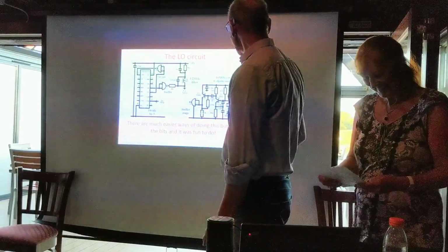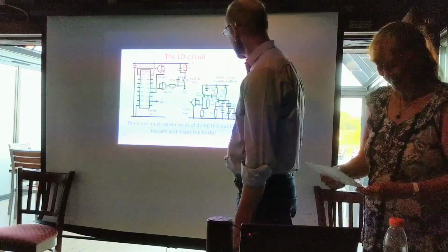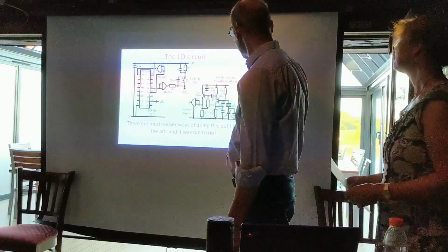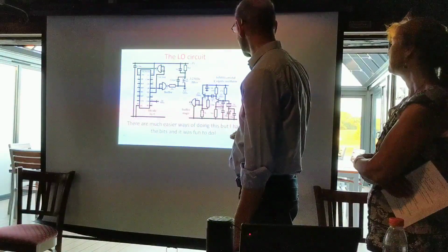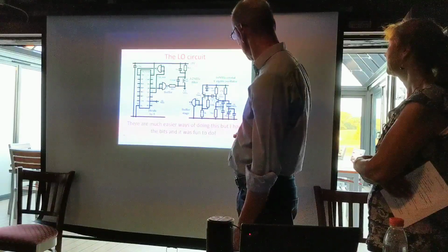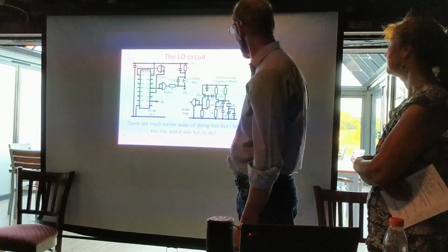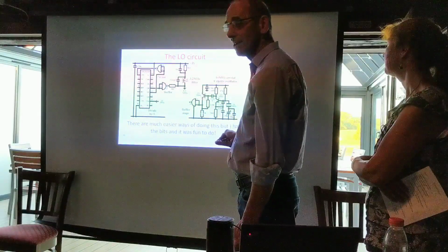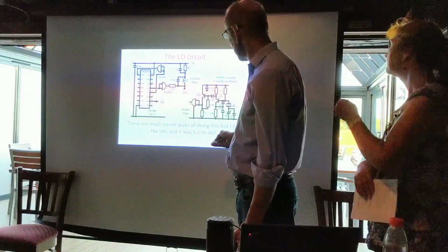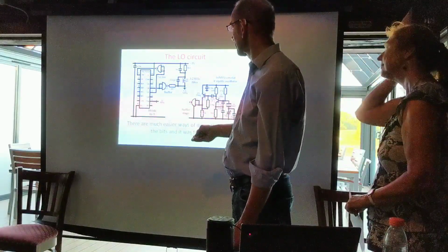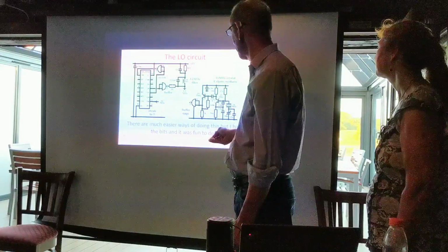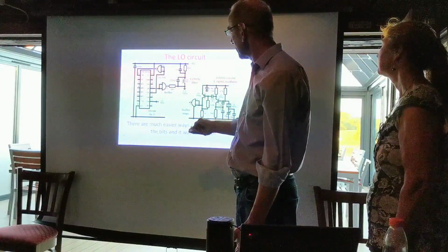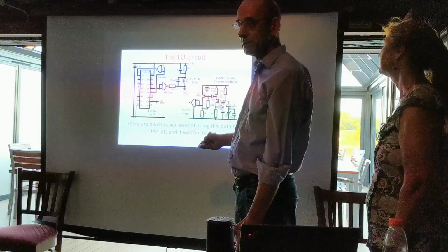So here's the circuit. All these circuits you can find on the internet. This is your basic Colpitts oscillator, crystal oscillator. If you put in 16 megahertz crystal Colpitts oscillator, you'll find that circuit. I put a little buffer on there, and it needs to be at logic levels. These things run on 5 volts, so you need to make sure the signal is 0 and 5 volts coming out here. This circuit is the presettable counter, like what Sue just told you.